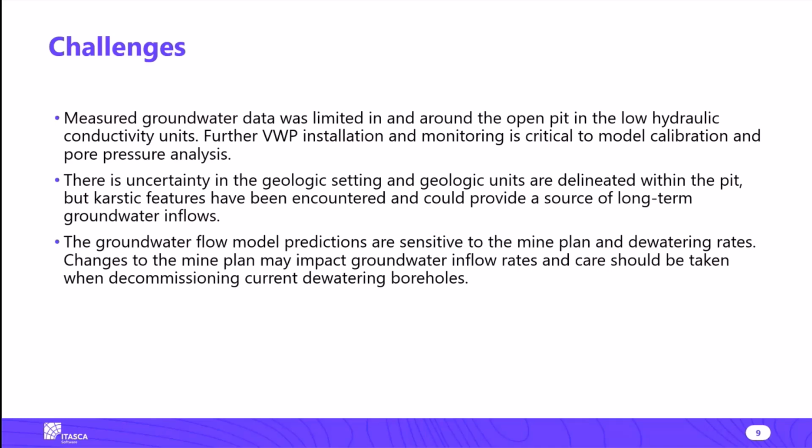As with any model, challenges arise surrounding the amount of data that is available and provided. In this particular project, groundwater data was limited around the pit and in the low conductivity units where high pore pressures may be a concern. Limited groundwater level data makes calibration more difficult and can affect the accuracy of the model.